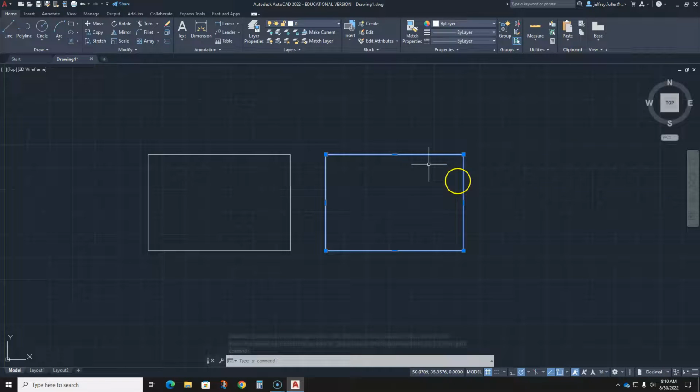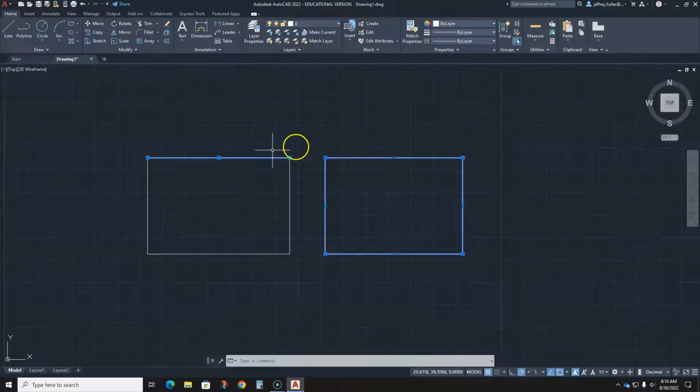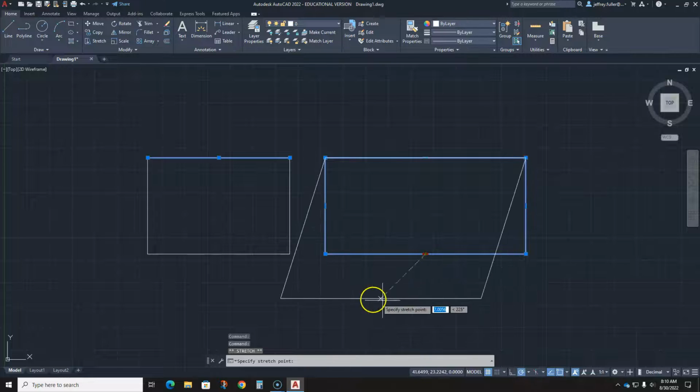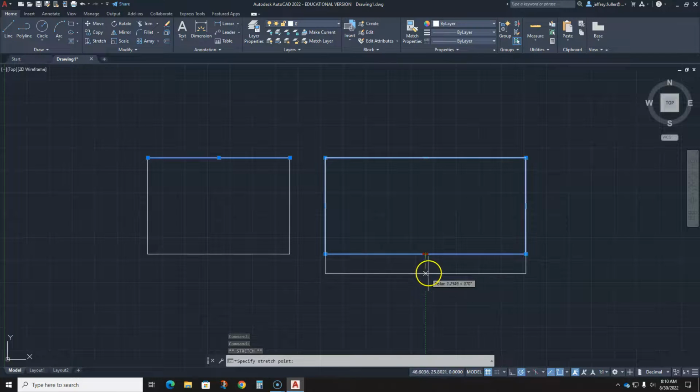And it has different center grips. If I click on this one, you see my center grip is a rectangle. And when I click on the entire poly object here, then my center grip is more like a flat rectangle. You can compare the two and see. Now what that allows me to do is grab a hold of it, pull it, and I can edit it that way instead of just pulling a line and then having to meet up with all the other lines. And I can also go with angles as well.